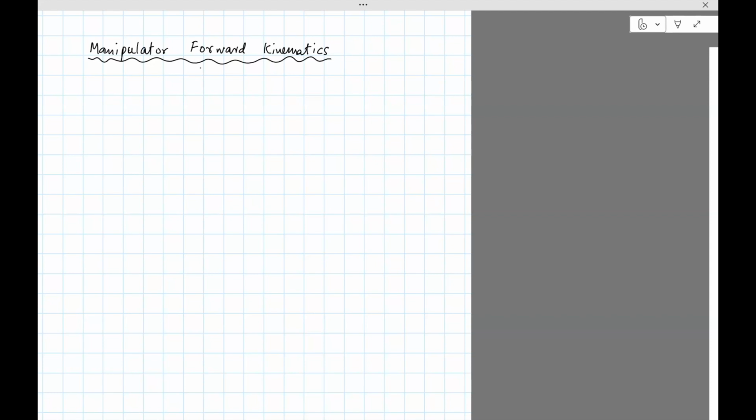The video I posted you was about the notations I was going to use in the class for translation as well as rotations. You can combine them with the vector formula I gave, but then there's a better way of writing those equations using what I described as homogeneous matrices. And if that was sort of vague, I think this will make it more clear, because this is actually applying what we did to derive equations for the forward kinematics of the manipulator.